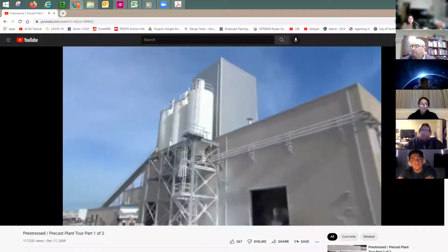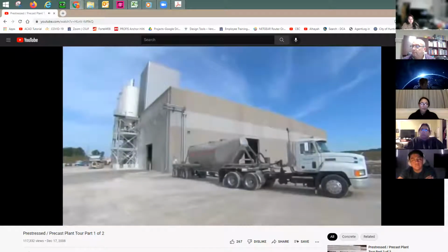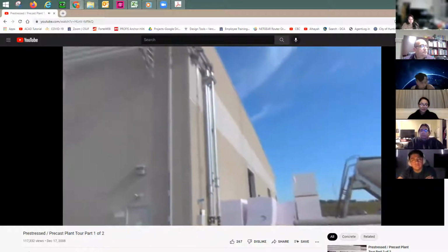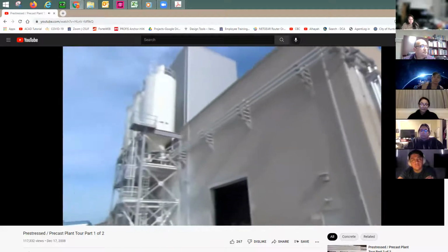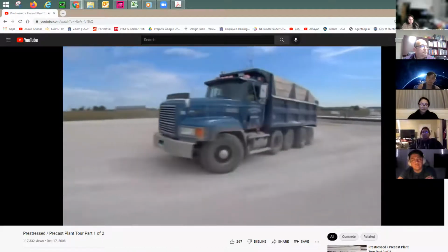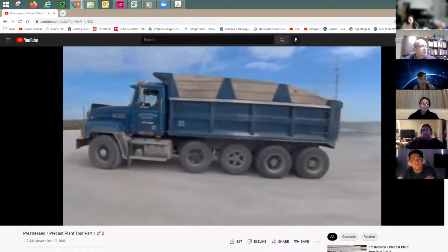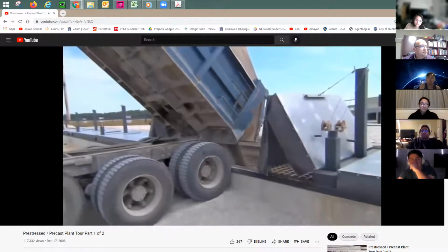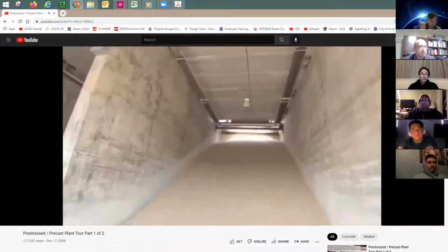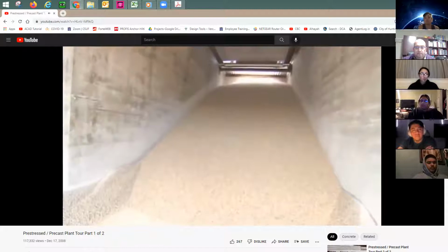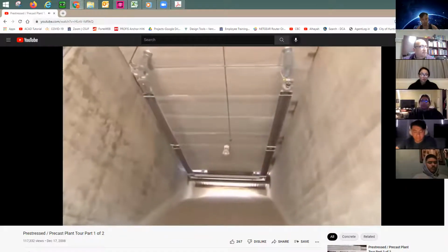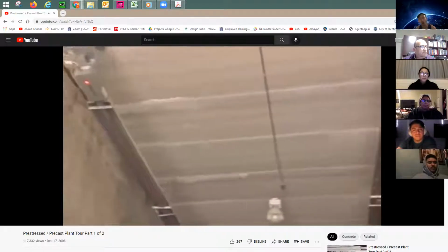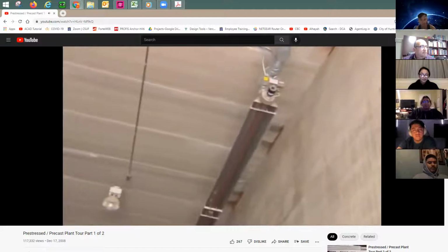Concrete is mixed at the batch plant under tightly controlled conditions. The cement is supplied using tanker trucks. Here, the cement is being blown from the tanker through piping to the cement silos. When needed, aggregates are delivered to bins in the batch plant. The aggregates are stored outside of the batch plant in separate bins. In this case, an enclosed vertical bin system is utilized. During winter, in northern climates, the aggregates must be heated to get them to flow properly through the batching system and to maintain proper concrete mix temperatures.